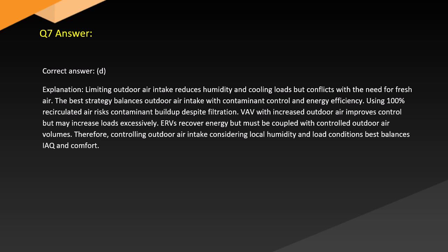Using 100% recirculated air risks contaminant buildup despite filtration. Valve with increased outdoor air improves control but may increase loads excessively. Energy recovery ventilators recover energy but must be coupled with controlled outdoor air volumes. Therefore, controlling outdoor air intake considering local humidity and load conditions best balances air quality and comfort.